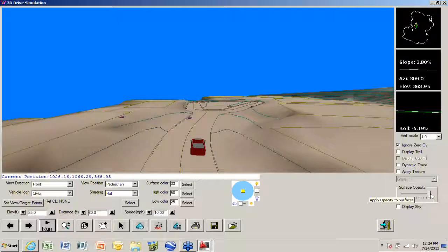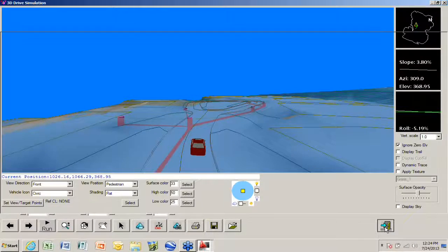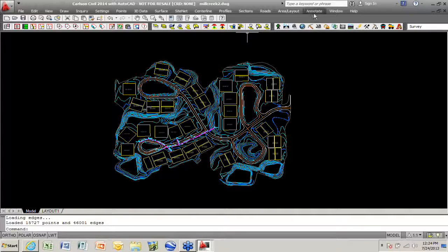I think this is something that's going to be critical for checking for conflicts, being able to look and see where structures are at. So even if you got these pipes from field to finish that I showed you earlier, you'd still be able to see those pipes underneath the surface. So this is a new command that's over here so that you're able to see the transparent surfaces there. All right, let's keep on going.